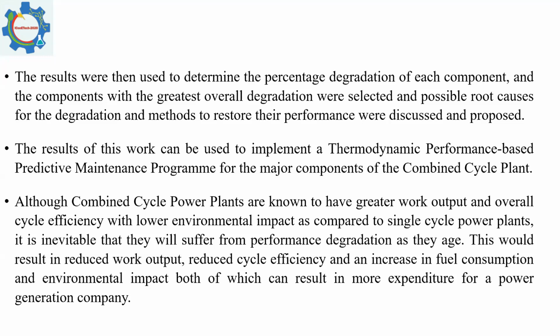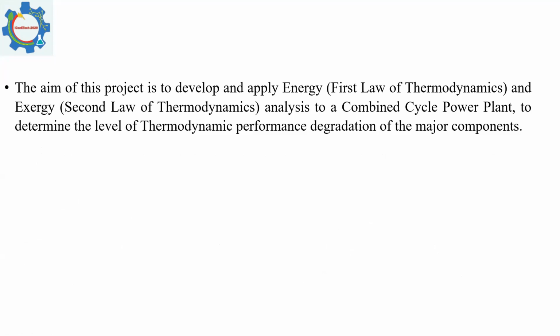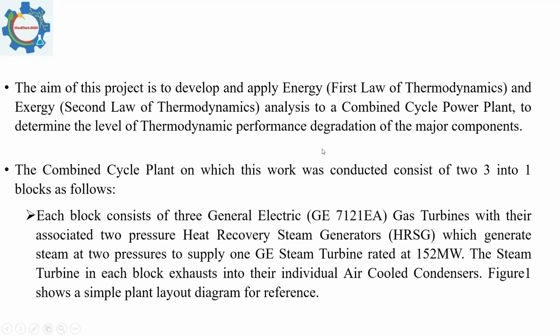The results of the work can be used to implement a thermodynamic performance-based predictive maintenance program, which is a further step on a process parameter predictive maintenance program for all the major components on this plant. And that is where the benefit is, so that a plant operator would have this program running whereby it actually computes the actual performance parameters, compares them with the design performance parameters to determine the level of degradation and performance.